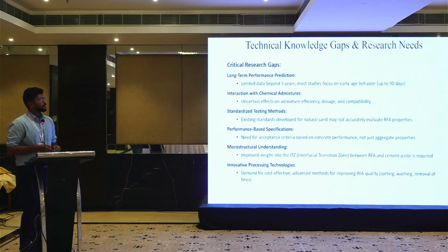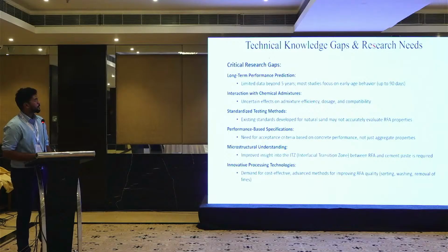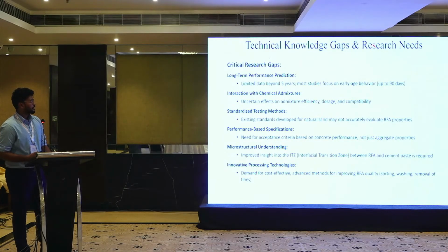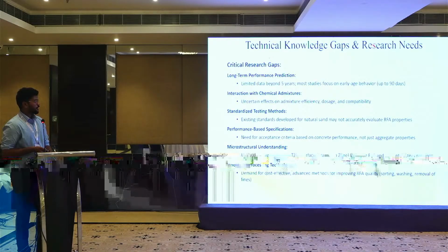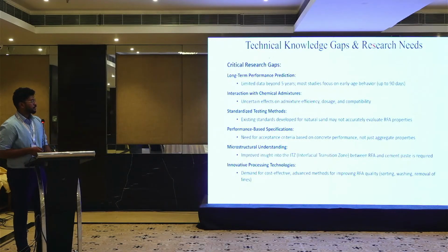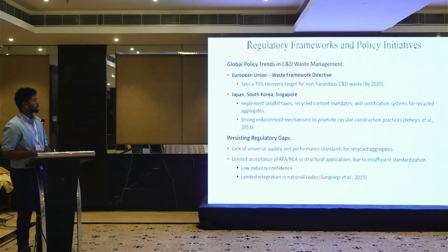Technical knowledge gaps and research needs. Long-term performance predictions: there is limited data beyond 5 years, and most studies were only up to 90 days. Interaction with chemical admixtures: uncertain effects on admixture efficiency and dosage. Standardized testing methods need to be implemented, and performance-based specifications are needed for acceptance based on concrete performance. Microstructural understanding needs to be improved; insight into the interfacial transition zone between RFA and cement paste is required.